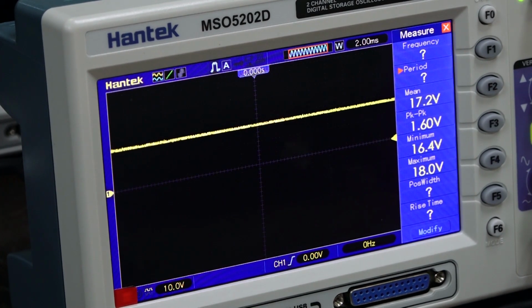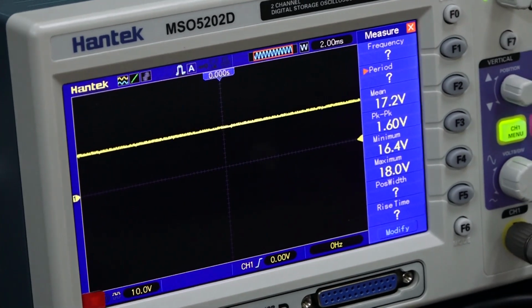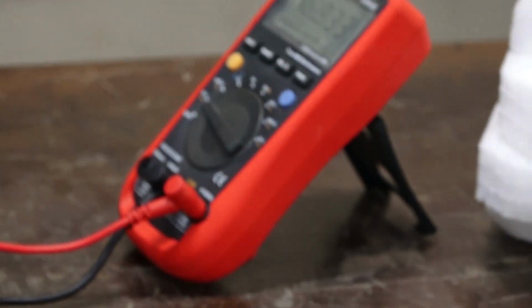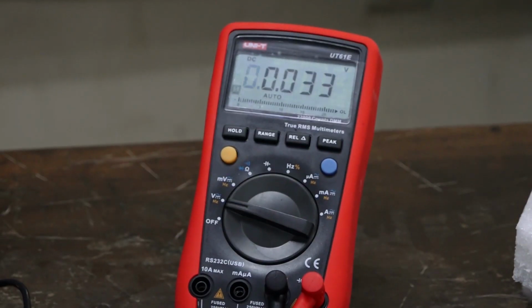Until you cross-check, give me the range when you measure the output of the filter unit. 17.20 something, others 18.20 something. And you see the digital oscilloscope telling you the same story. But if you forgot, that is fine. We have a digital multimeter and this is a DC signal. So we have to measure the voltage across the filter unit. For the digital multimeter, how many volts?